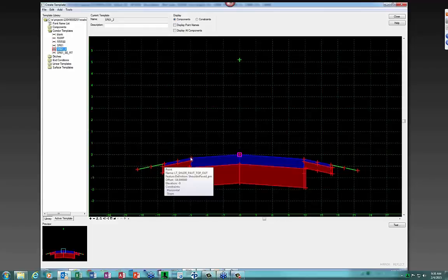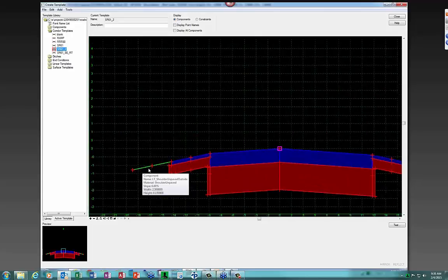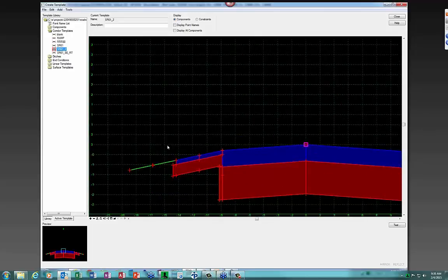So you've got, here's the normal shoulder, or the edge of pavement beginning of shoulder, and then you've got 1, 2, 3, 4 points out here. Well, these points are for rollovers, and you may or may not need them all. It all depends on how your physical shoulder is. Do you have 5 foot paved, 5 foot unpaved? Do you have 2 foot paved and 8 foot unpaved? Do you have, whatever combination? The middle point that needs to break may be either in the paved or it may be in the unpaved.